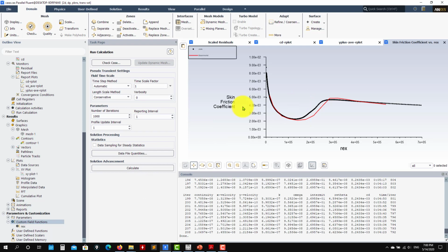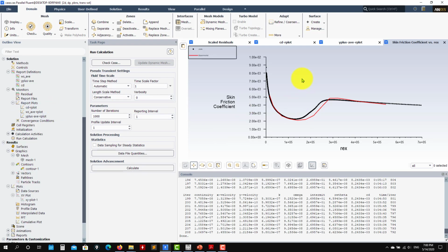So let's rerun this case, just to show you what happened. If you go laminar, you will see that this will fit to this one fully. If you go turbulent, it will go here and will stay here, as I showed you at the beginning. What I was mentioning during the lectures is to have in mind that CFD solutions from the fully turbulent models, the models that do not address transition to turbulence, fit very well the forced transition simulations or turbulent solutions.